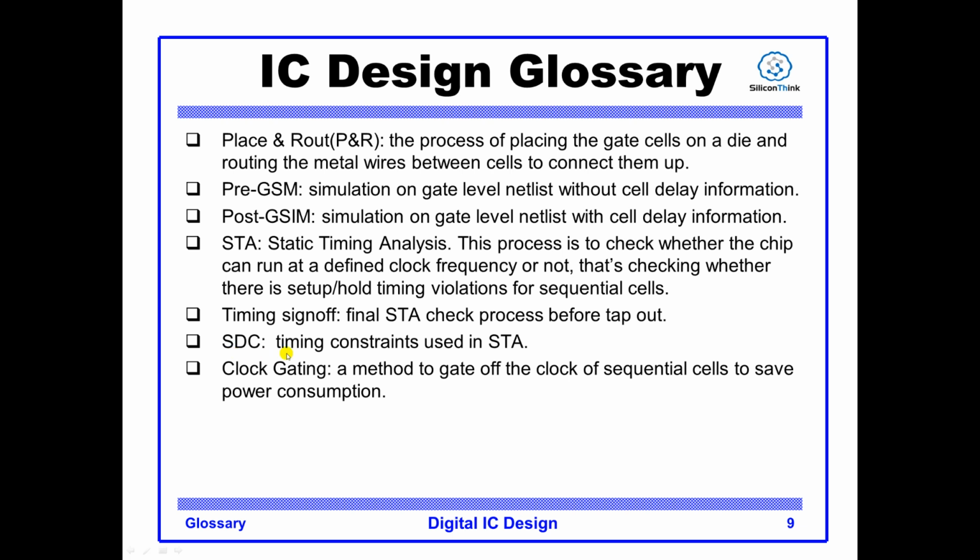SDC, standard delay constraint. This is a timing constraint used in STA. For example, you need to define the clock frequency in SDC. SDC is a constraint to help the STA tool analyze the setup and hold timing of sequential cells. Clock gating.